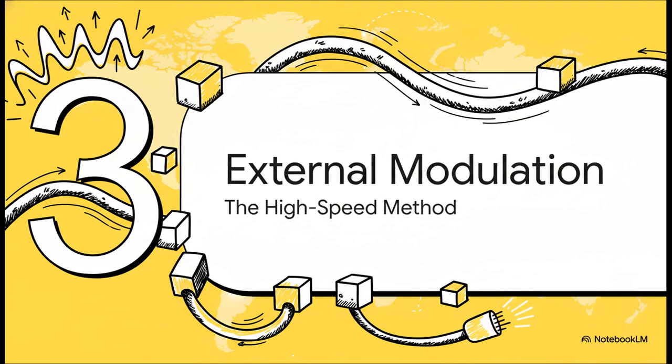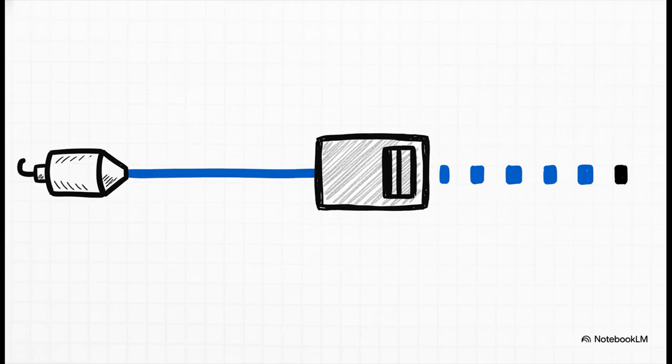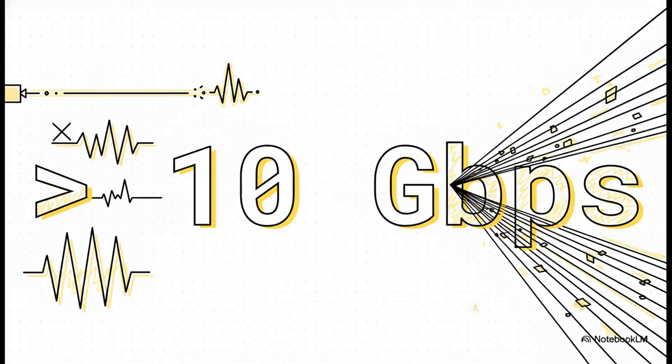So now, let's meet the hero of high-speed communication, external modulation. This right here is the strategy that powers the very backbone of our modern internet. Now, the whole philosophy here is completely different. Instead of messing with the laser itself, you just leave it on. You let it produce a perfectly stable, continuous beam of light. And then you place a separate little device in its path that acts like a super, super fast shutter, literally carving the ones and zeros into that steady beam. And because that laser source is totally stable and there's no chirp to worry about, this method can handle much, much higher speeds. We're talking routinely exceeding 10 gigabits per second and going way, way beyond that. This is the tech that's built for the data superhighway.